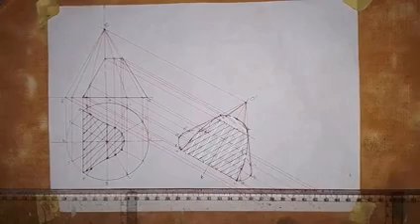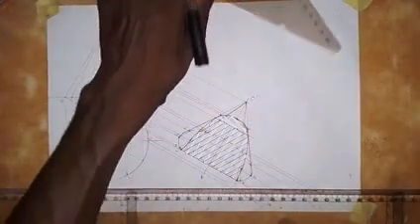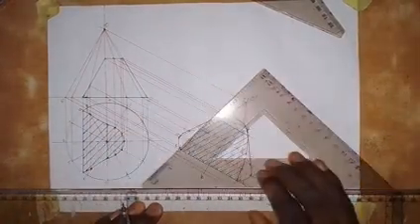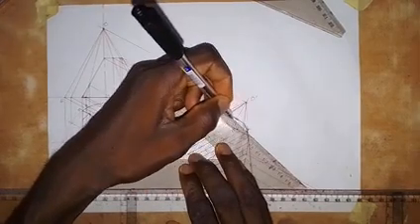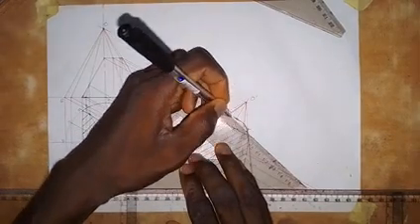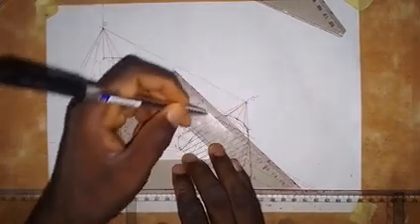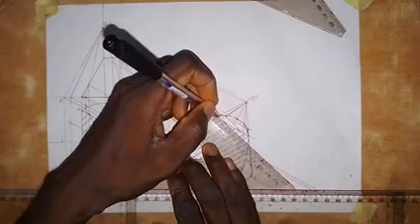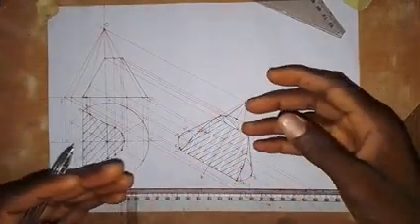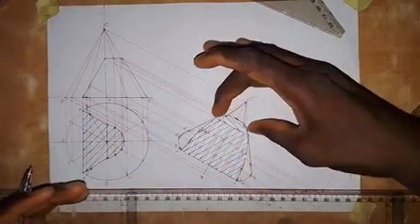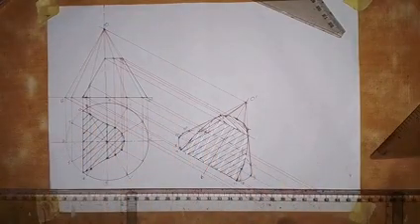Alright, so this is okay. Now let's go for this upper one. I'm going to use 45 degrees for this one, but I'll produce it in this direction. So we have to change the direction of the arching lines. Alright, so this is how it should be. The reason we have it arched in different directions is that this is one surface and this is another surface, so they have to be arched in different directions.